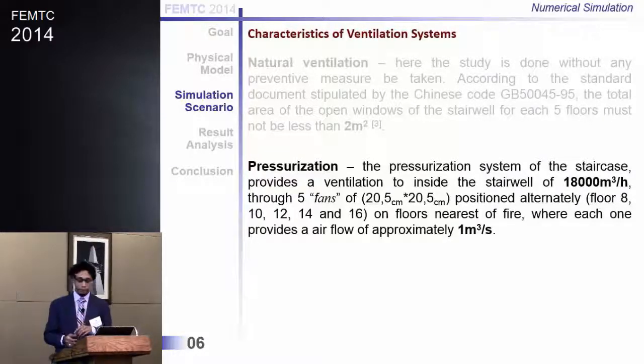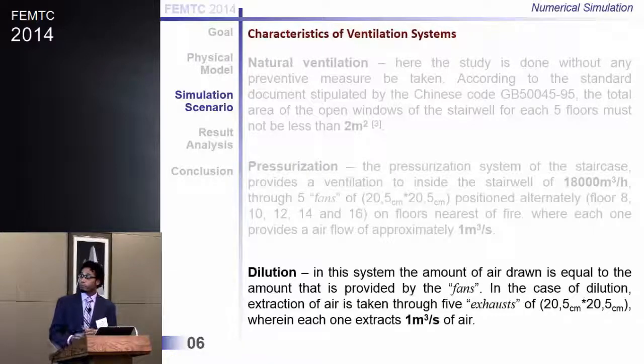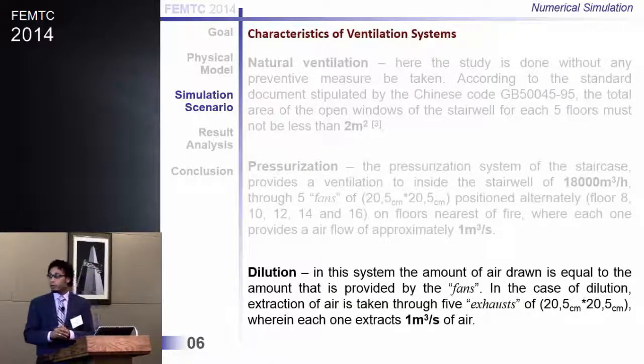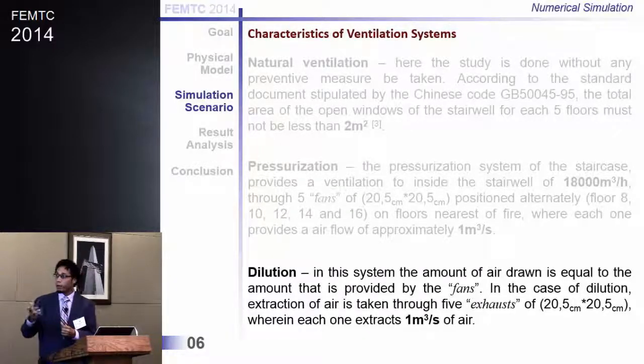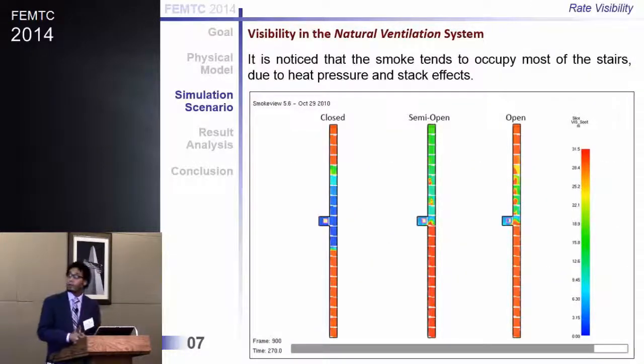For the dilution, we use some exhaust, and we should clarify that the exhaust should take off the same quantity of air as the pressurization supplies to the indoor stairwell.